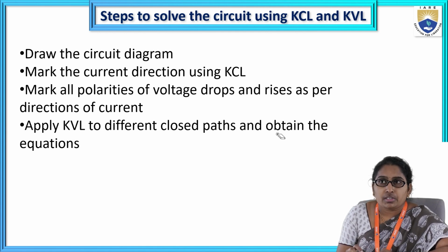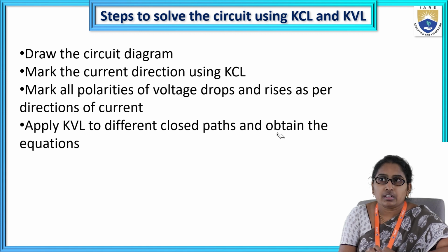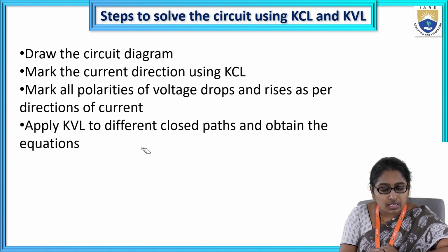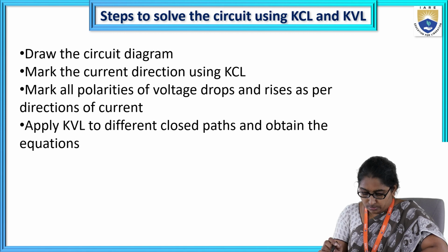So after taking the circuit, they mark the currents according to KCL, then mark the polarities of voltage drops according to the directions of currents. Last step, apply KVL to different closed paths, obtain the equations and solve them. Okay, so look here.